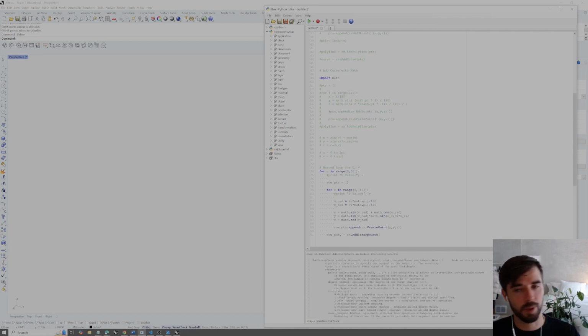And then we can just open up this parentheses, and interpolate curve is going to draw a curve exactly through the points, but smoothed between them. So it's similar to a polyline, and we went over this in the Rhino introduction, but it draws exactly through and kind of smooths between those points. And now what we need to feed in here is a list of points, as it says in our help document at the bottom, so we can feed in our row points.